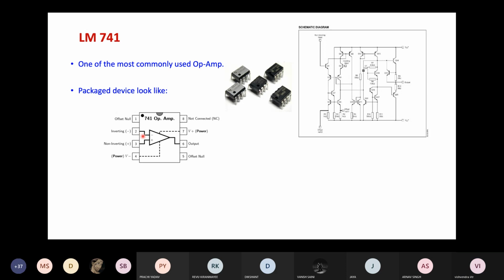This is the general convention whenever we number the pins in any IC. Okay, so if you come across any IC and somebody asks you where is pin number 6, you need to count like this, okay? And this dot here, or this kind of dot, shows that it is the top of the IC. So we need to see from that side. On the left side, 1, 2, 3, 4, and then from the bottom, 5, 6, 7, 8.